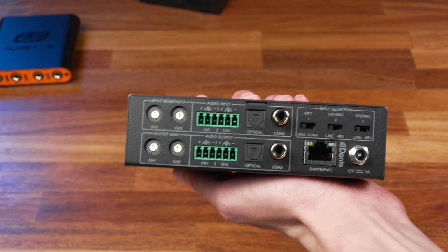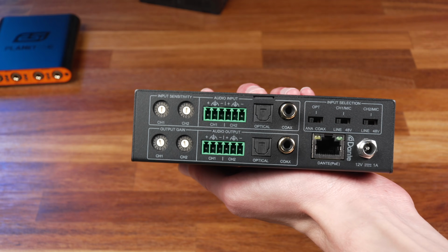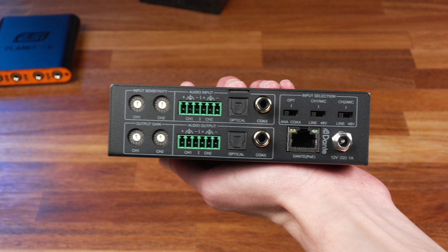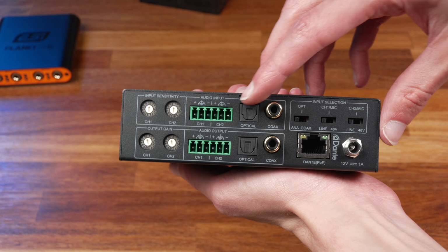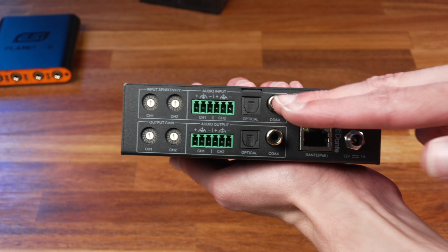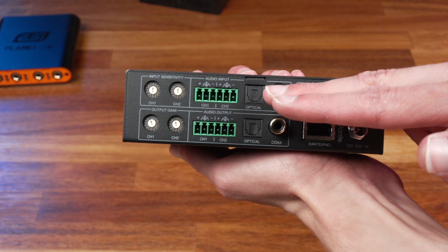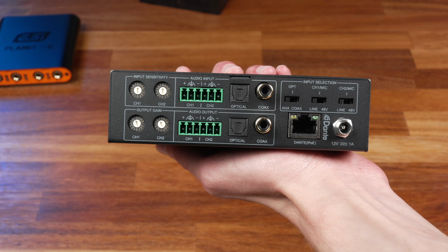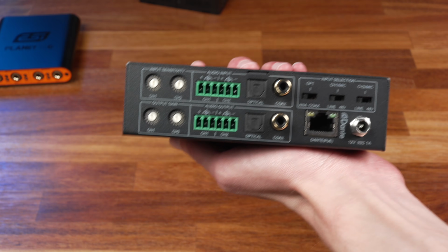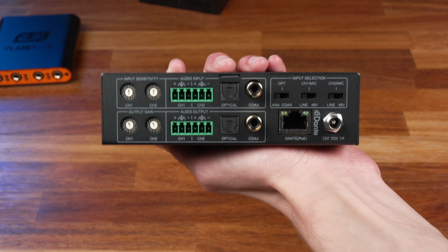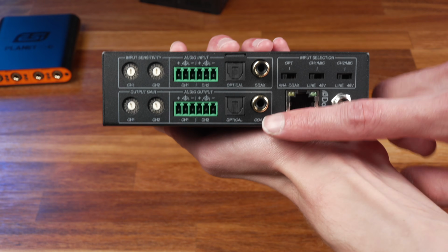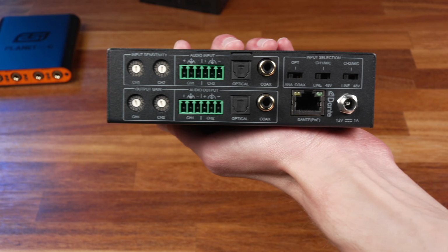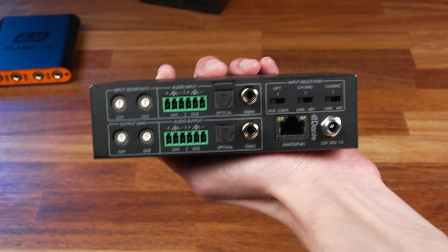I'll just need to make up a couple of cables to go from the Phoenix connectors on the back of this to RCA plugs. Then next to that we have both optical and coax connections for digital audio, and as you can see we have two different rows of these connectors, the top ones being inputs and the bottom ones being outputs. So with this I can plug the downmix stereo RCA outputs of my receiver into the analog inputs on this, and then I can connect the optical audio output of this into one of the optical inputs of my receiver to feed audio from the multi-room system into the receiver.